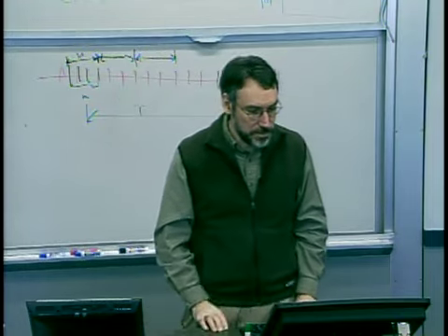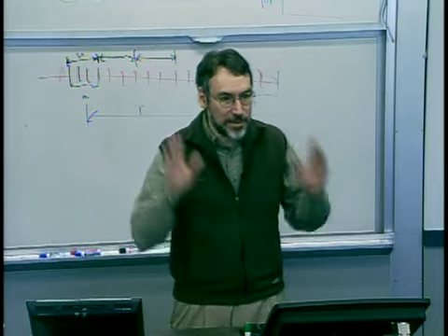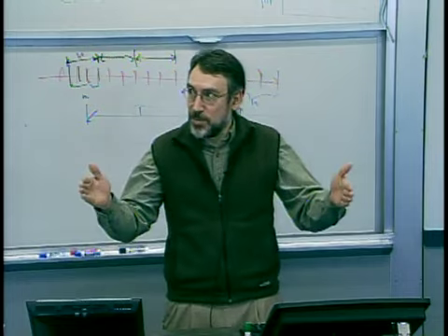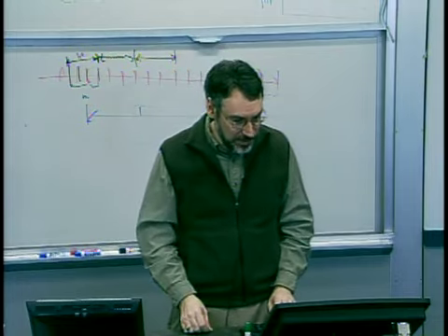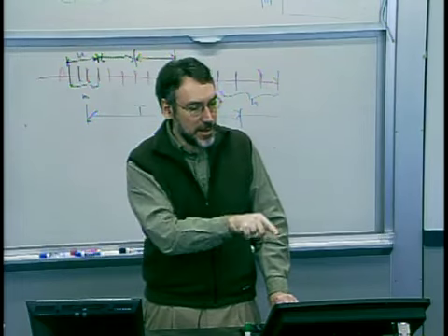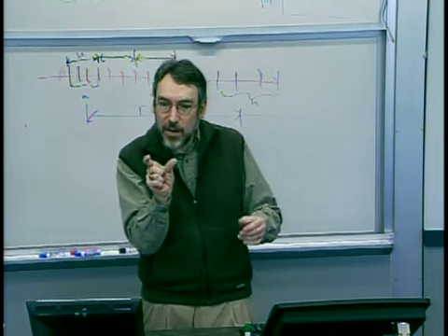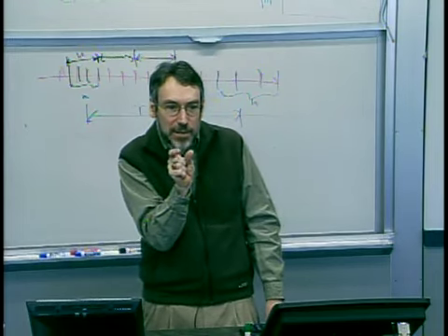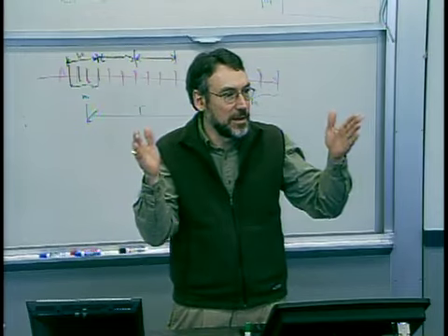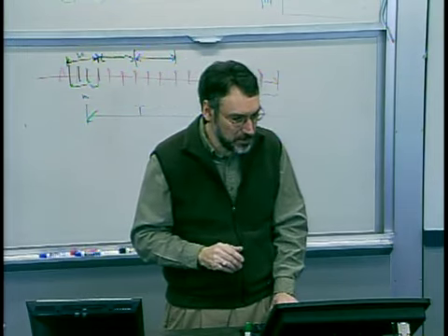Very good questions. So the key idea here on the process capability is simply talking about the spread in your process compared to your spec limits and how good that is. Notice that if I'm off target, this definition, CP, doesn't change. This is purely talking about the inherent variance, the inherent spread in your process compared to your spec limits. Your inherent 6 sigma spread compared to your spec limits.